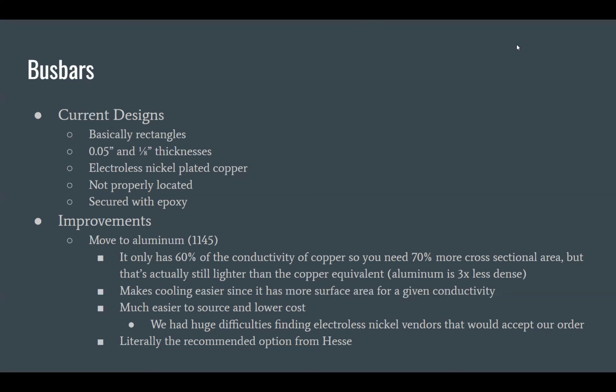You now need to have this really big hunkin' bus bar. And the way that I sort of recommend it is, like in here, obviously we made them these super thin strips. The recommendations I've seen on most battery packs is they just make them as big as possible. They will make it cover the whole surface. And that's okay, because when you make it super big, it's better conductivity and it has more thermal mass. So it actually won't heat up as quickly and it can radiate more effectively. You can get into a situation where if you make your bus bar really big and fill up a lot of space, then it will actually never overheat when you're running it normally, and then you don't have to actively cool it, which would be super cool.